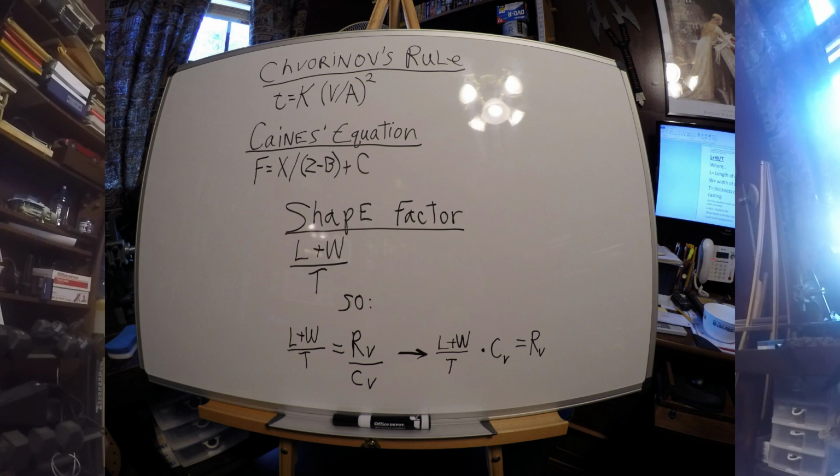Now, one of the ways that you can use to find out casting volume is you take a container that the casting can fit in fully, fill that container up with water to where it's just almost overflowing. Set up a way that you can catch water into another container, and then slowly lower that casting into the larger container.